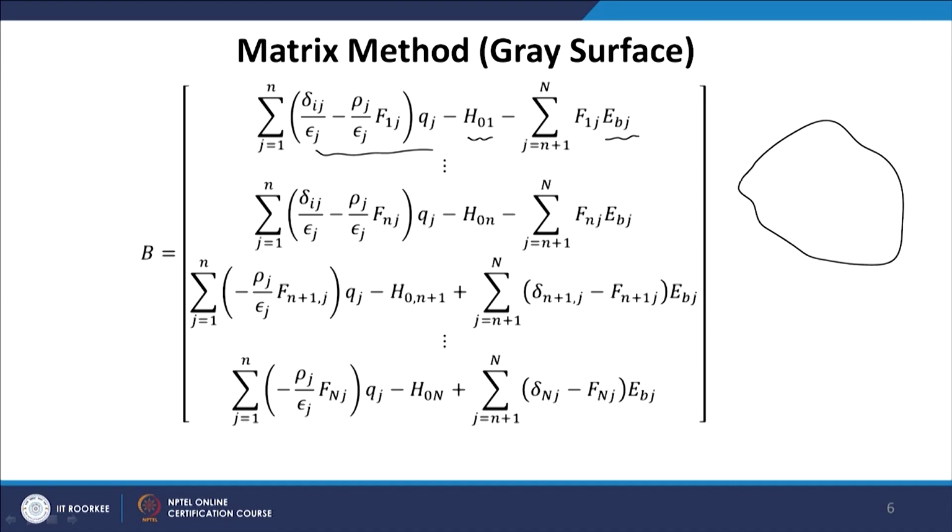Okay. So, I again recap why we call it an idealized enclosure, because we have divided the enclosure into a number of finite surfaces, which may not always be good in all types of problems. For example, if we have a surface, okay, and let us say we want to maintain or heat this surface uniformly over the entire area.